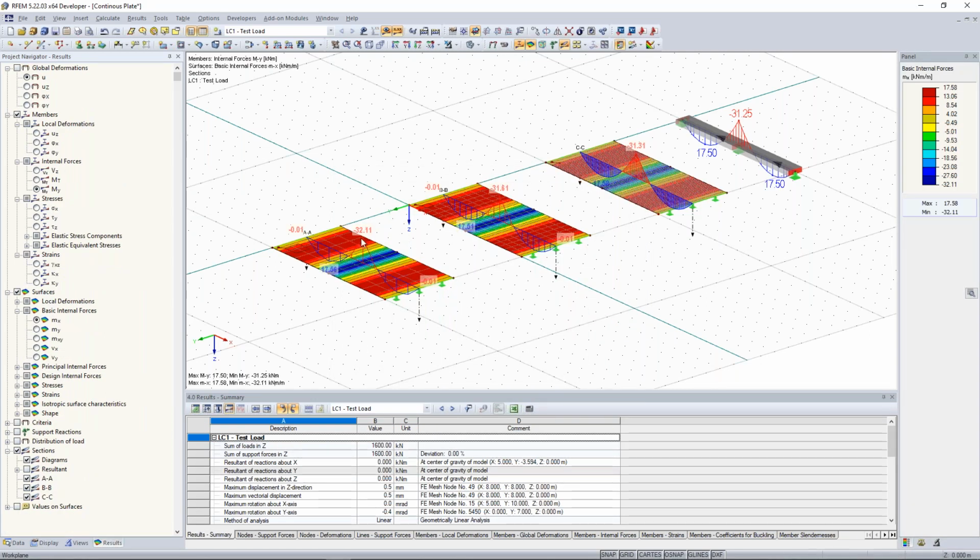So, and here you will see now the different results. So there's a difference. And the greater the thickness of one plate is, the greater is also the difference between these two calculation theories. My recommendation for you, please use Reissner and Mindlin. Then you are always on the safe side.